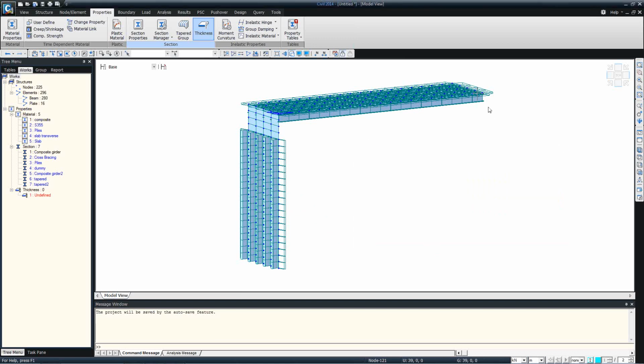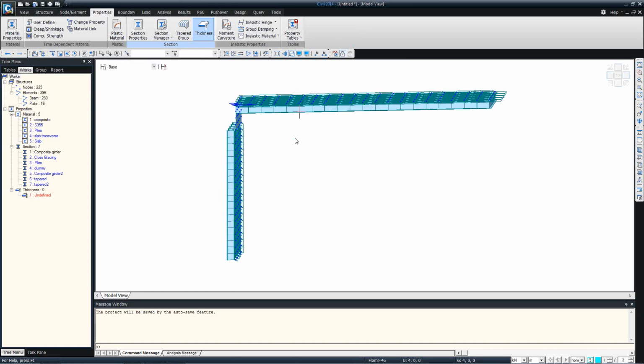So always break your arc into several segments and import them into Midas Civil. Because the software directly deals with mesh, there is no so-called geometry involved, and you will get to know the reason behind it, because the options available for geometry modeling are fairly simple within the software. So you can directly create the mesh as if it resembles geometry itself. So I'll go through some curved geometries as well in this example. We'll look at curved bridges, and then I'll cover how to model a horizontally curved bridge. So I hope that answers your question, Riza.